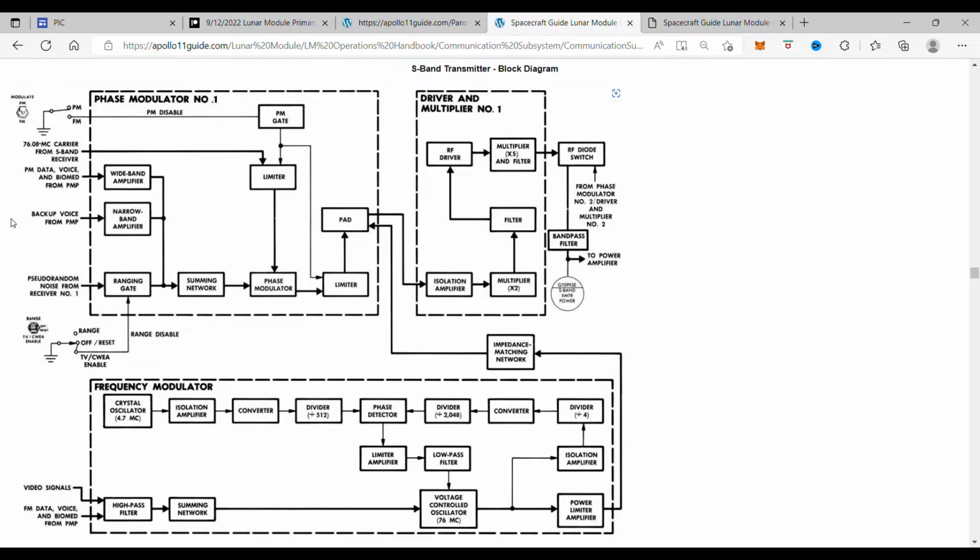In flight, S-band communication between the Lunar Module and Manned Space Flight Network, MSFN, while the Lunar Module is on the Earth side of the Moon, include voice, digital uplink signals, and ranging code signals for the MSFN. The Lunar Module S-band equipment transmits voice, acts as a transponder to the ranging code signals, transmits biomedical and service and systems telemetry data, and provides backup capability and an emergency key capability.